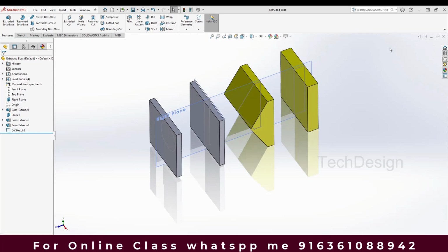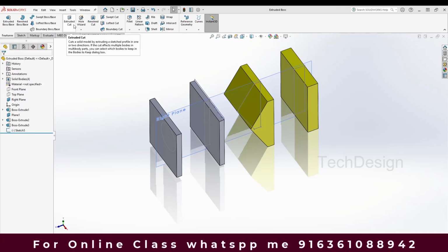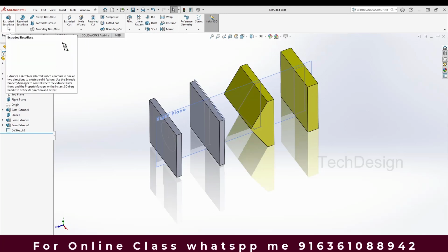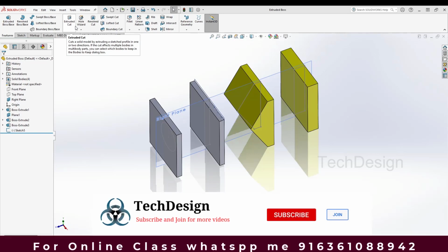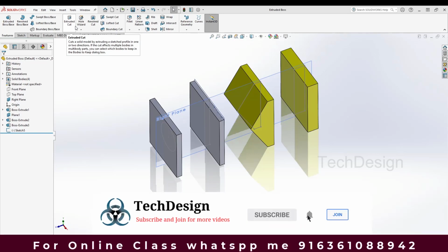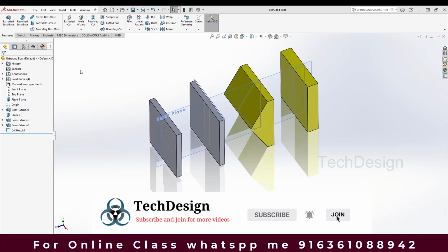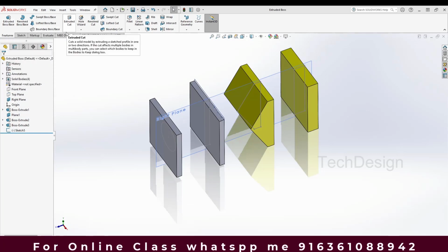You can see here, this is the Extruded Cut command, because these two commands are very similar. The only difference is that Extruded Boss is going to add material, whereas Extruded Cut is going to remove material. So in the end of this video, I'm going to demonstrate the difference between these two commands.